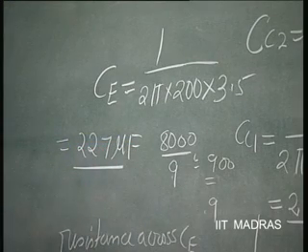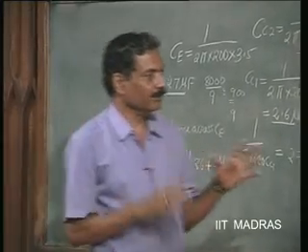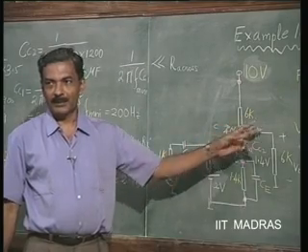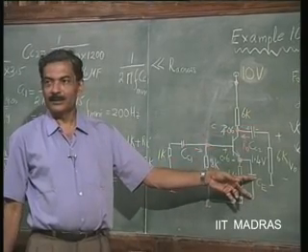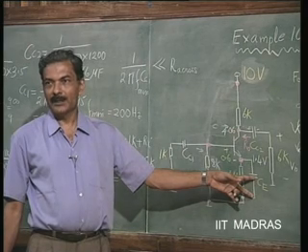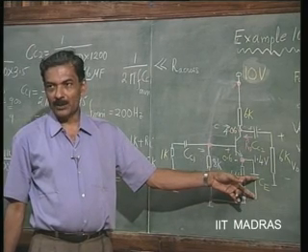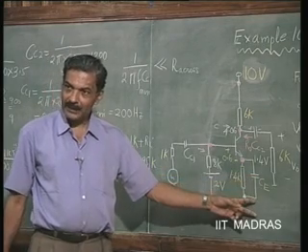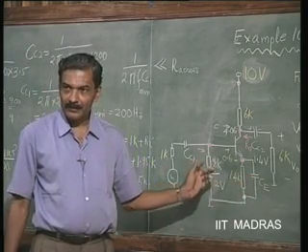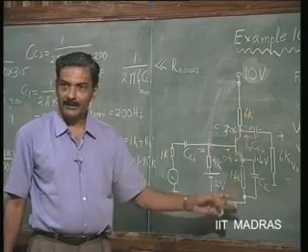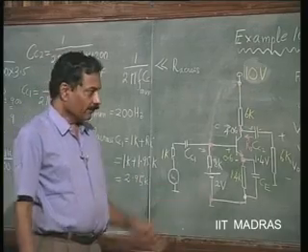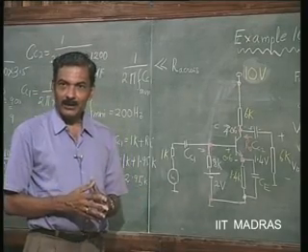You will see that in a typical design, it is the highest capacitor that is costlier than the other capacitors. So, this is the one which determines really what is called the lower cutoff frequency. If they are not acting as short circuits, they will reduce the gain, they will take away some voltage here, and some voltage here.